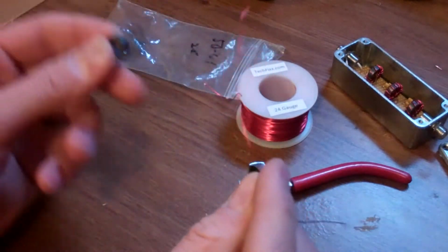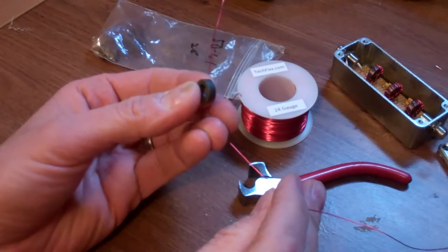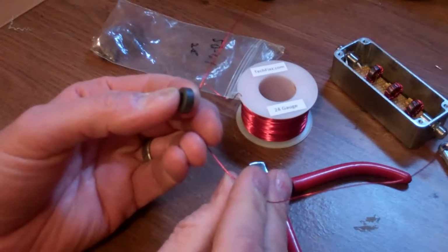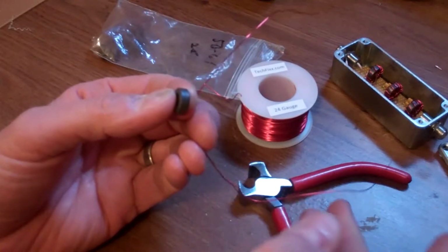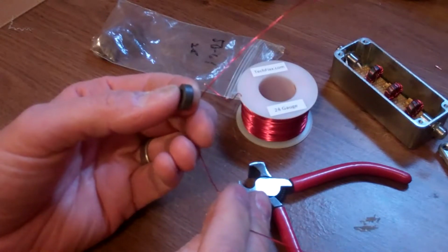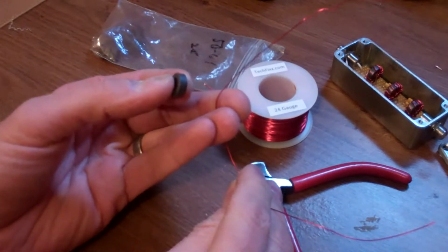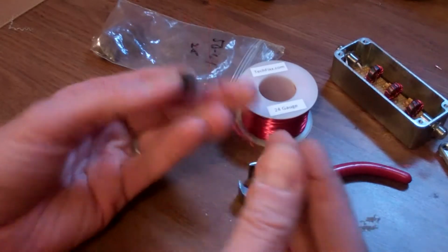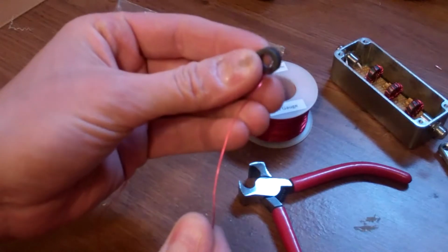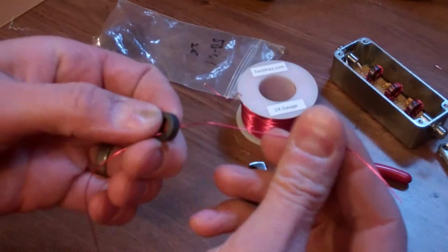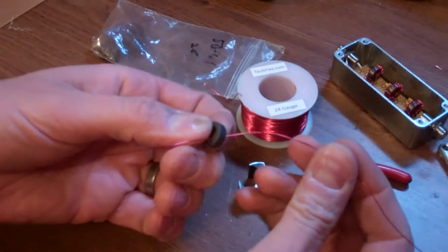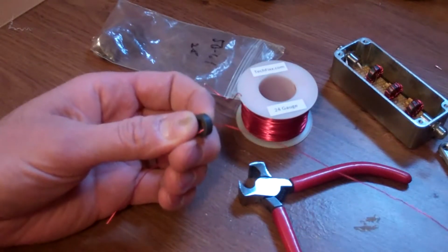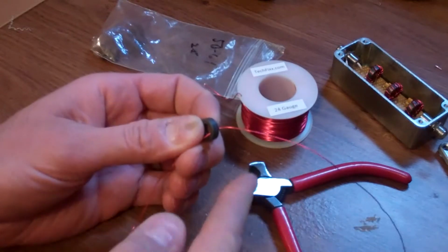But basically the toroid calculation program that I showed earlier even tells you how long of a wire you want, with a little bit of extra for the leads. So I always take the value they give me, and then I add a couple inches on either end for that. But basically, once you've got your length of wire and your toroid, just put the first loop through. I always like to start on one end and finish up on the far end. Some people like to start in the middle and go from either direction.